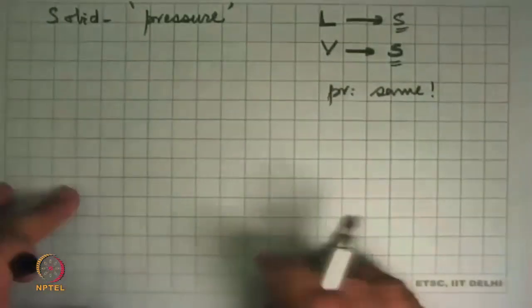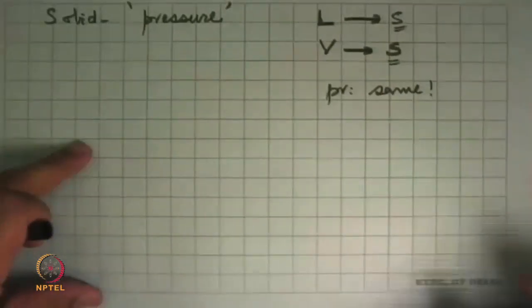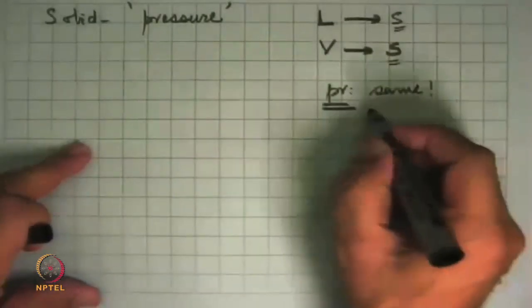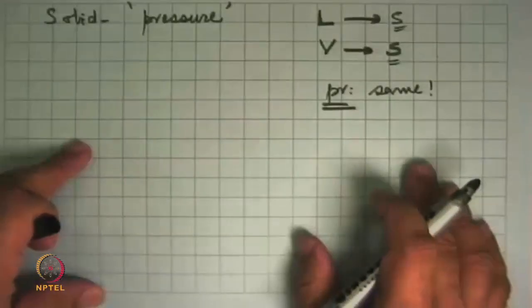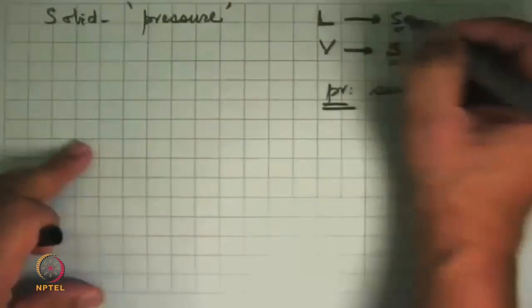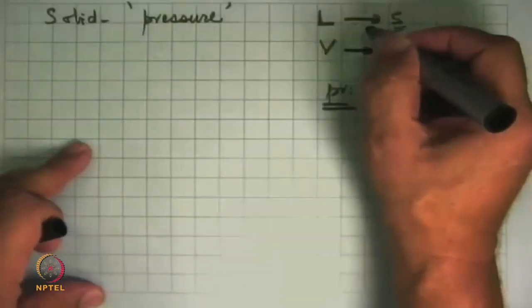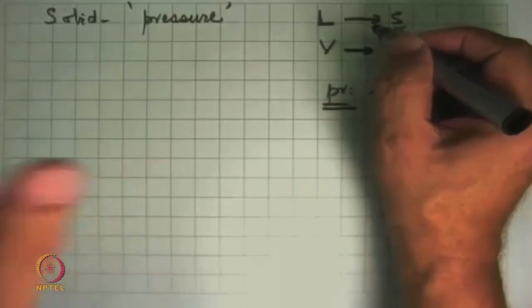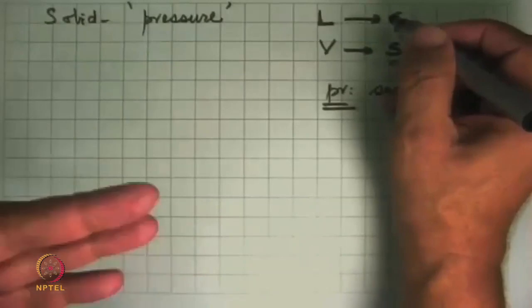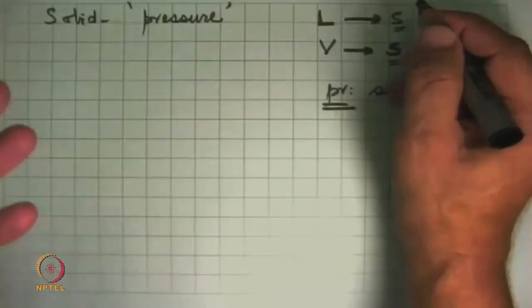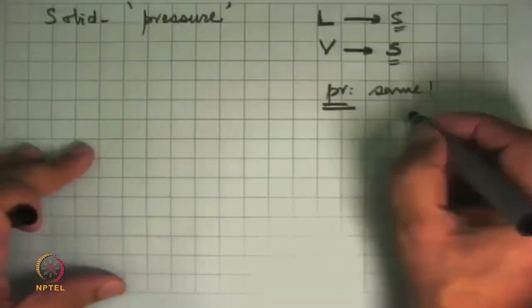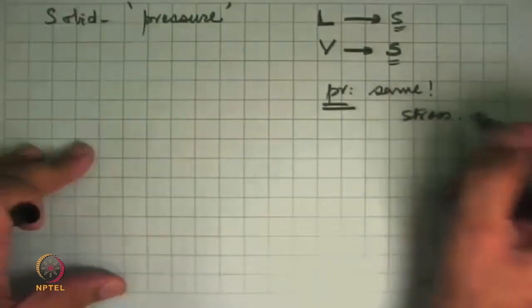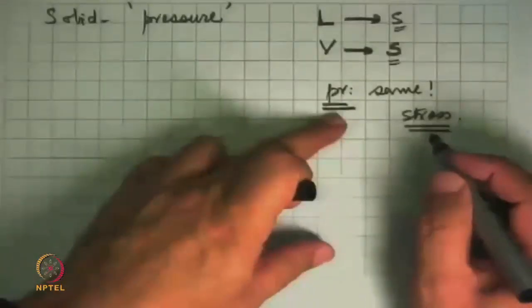But we know from our knowledge of solid mechanics and stress analysis that pressure is not defined for a solid. So the only thing that we can say then is that if the solid was made at a particular pressure, only at that temperature will the pressure inside be equal to the stress inside, which is the same pressure. If you further cool it, it will not be the same pressure, because stresses will develop, and stresses will cause internal average stresses to be different than what the hydrostatic pressure was.